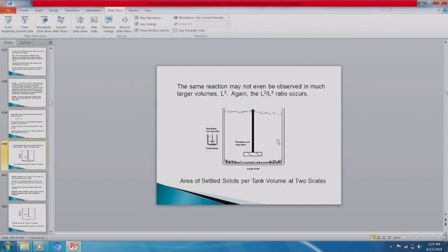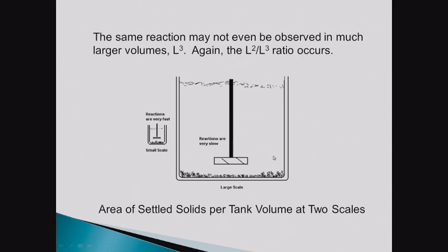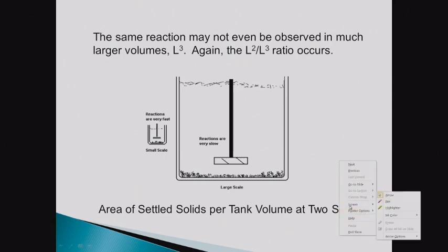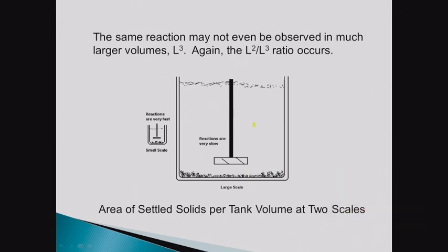This one is coming to you from Merck, Rahway, New Jersey. The idea of settled solids works fine here for this chemical reaction. For this chemical reaction, the solids on the tank bottom are not even noticed. So if I was to try to scale up this process, right? What I would want to do when I scale up this process is I want to make sure the solids go throughout the entire tank, right?